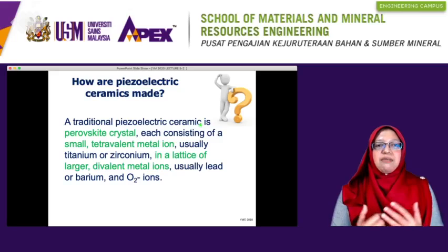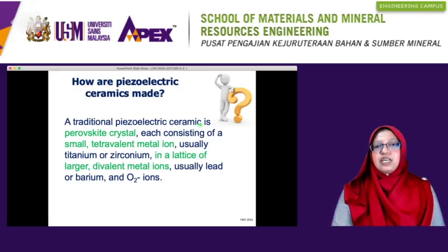So how is piezoelectric ceramic made? A traditional piezoceramic is a perovskite crystal consisting of small tetravalent metal ions, usually titanium or zirconium, in a lattice of larger divalent metal ions, usually lead or barium, and oxygen ions.